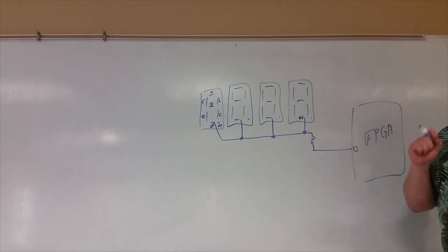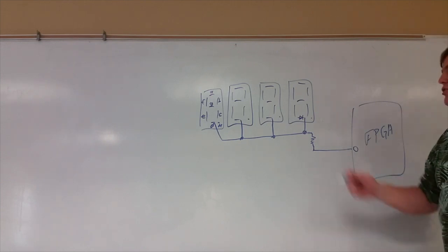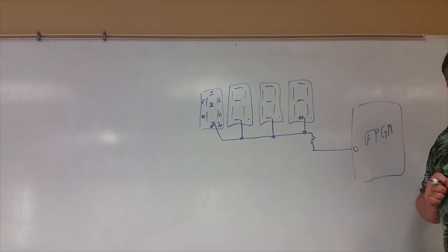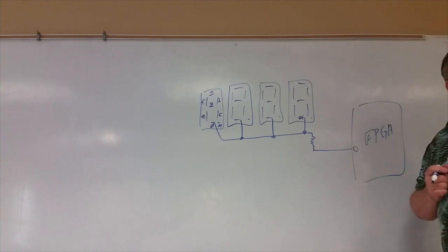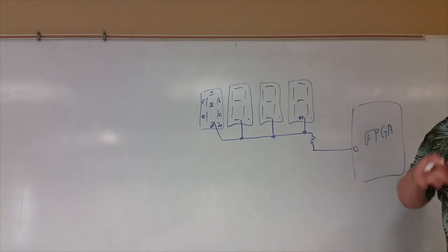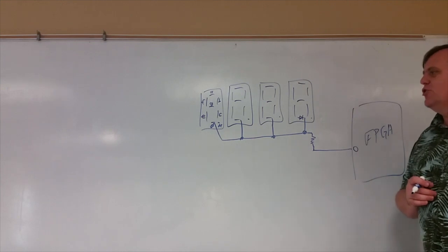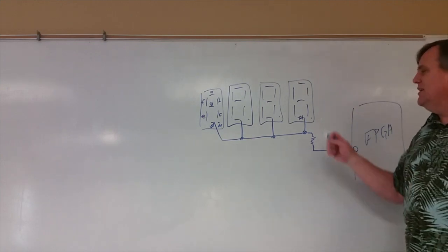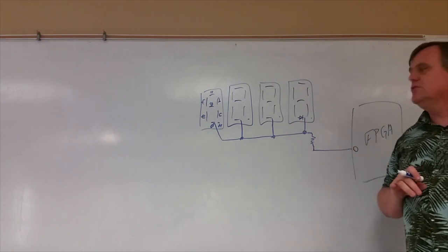So you give it, this is why this one is important to understand. You give it 0 to give it a ground. So if you write 0 to the anodes, you have supply to ground, right? This will limit the current, so I'm capable of sinking that current, and now you're good. That make sense? All right. So we've handled the first part. And imagine this thing is repeated for every other one of the things.